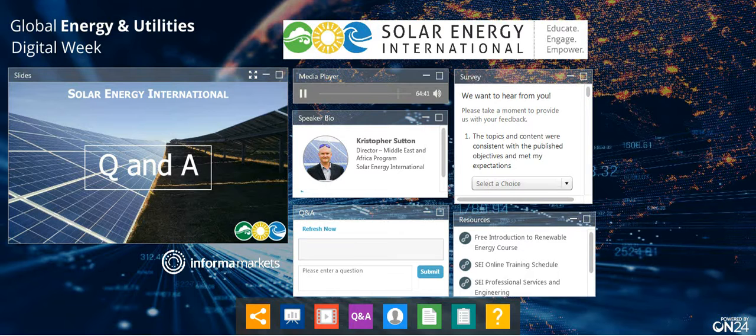Anytime we synchronize a generator and a PV system in that type of generator hybrid setup, we have to make sure that if the solar output is greater than the load, we don't let the solar backfeed into the generator. We can damage the generator by sending that energy there. So that's where the control system comes in. It's going to measure the load, the solar output, and the generator, so it will know the difference between the solar production, the generator production, and the load.